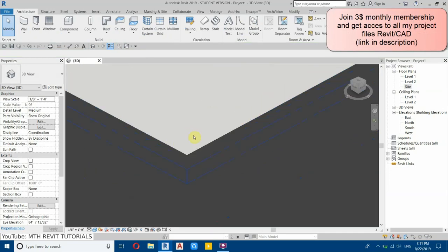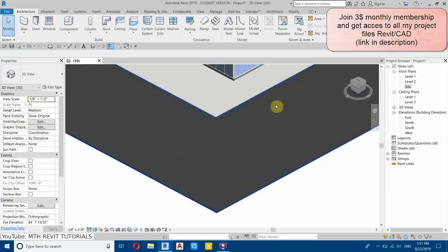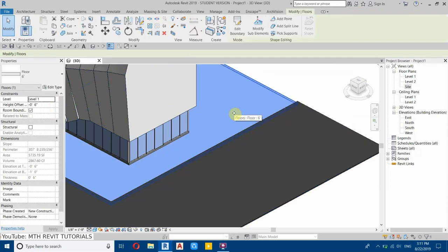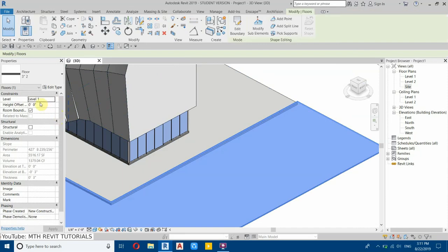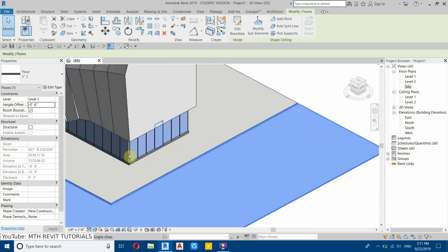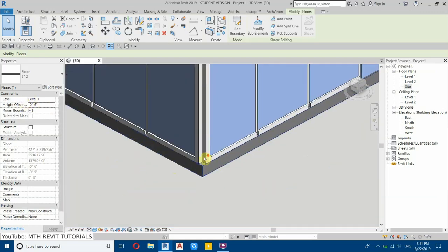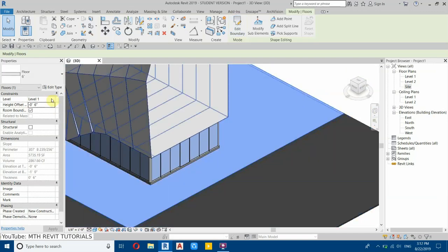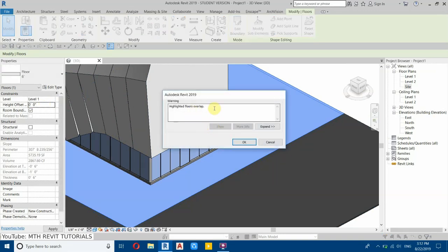So okay, we just need to take this down a bit. So the thickness of this floor is 6 inches, so we need to give a negative 6-inch offset to this road. Select that, minus 6 inches, or maybe you see there is already one floor here, so for this one, select that, we will remove the offset here, and then okay, just click OK.